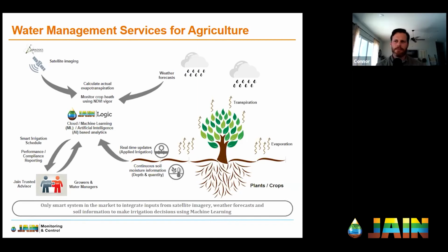Yeah, exactly. Just like the example I talked about earlier, that is the benefit of connecting up your flow meter and then having pressure sensors at the filter station and having pressure sensors out in the fields. Because a lot of times we have our pumps and our filter stations feeding multiple fields. So if we're pulling it from the ground, we can track how much water we're pumping through that site.